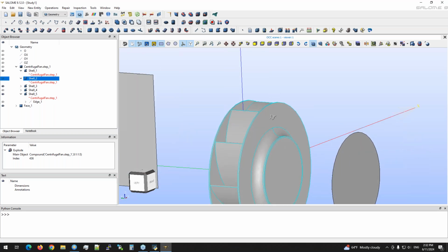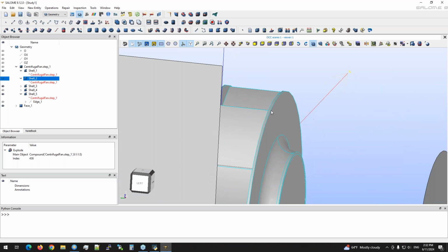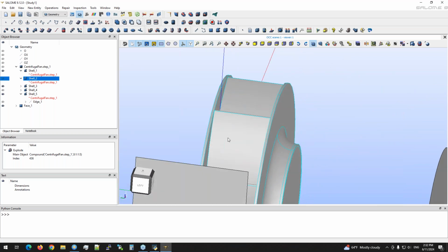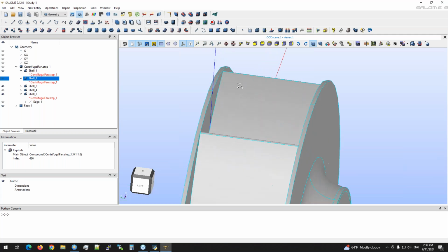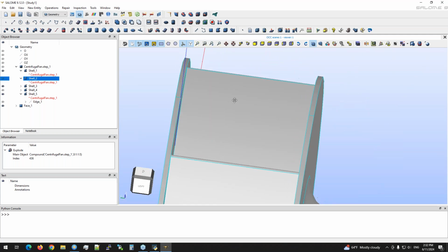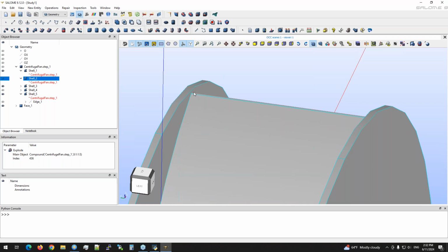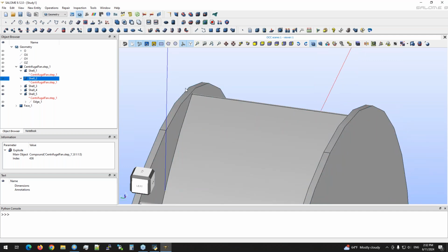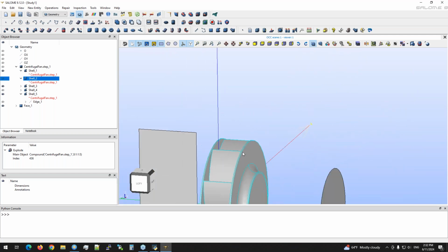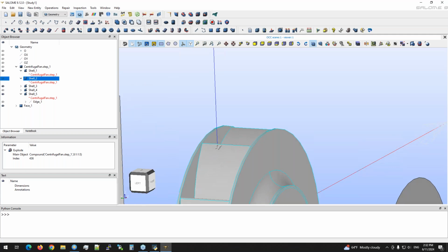Or the second option is to just include the rotating part only in the flow channel of the impeller, because of the meshing purposes. We need to mesh everything, and the mesh needs to have some kind of space to create, for example, small meshing at the trailing edge of the rotor and within the impeller area. So let me do the second option.